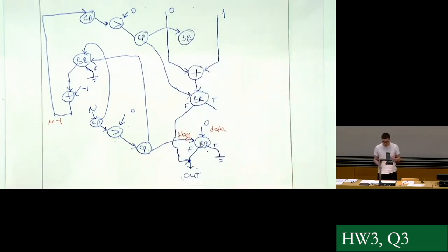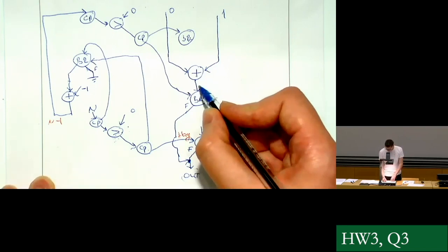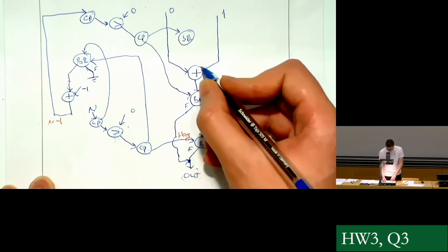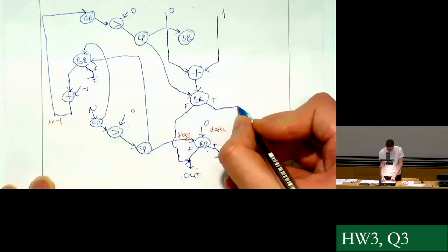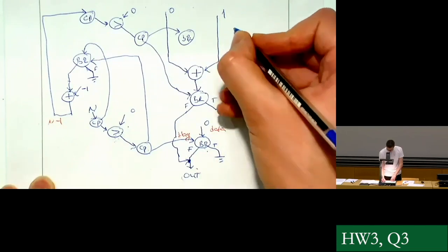Okay, so now we have it working for the two cases, 0 and 1, which were the hard-coded values for the Fibonacci sequence. Now we'll make it work with any arbitrary n. For that, we'll create a loop where this result is forwarded on the true path back to this addition logic. This will need to be connected here.